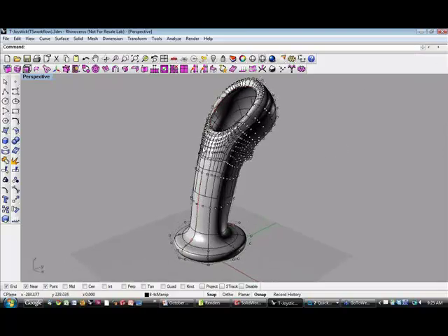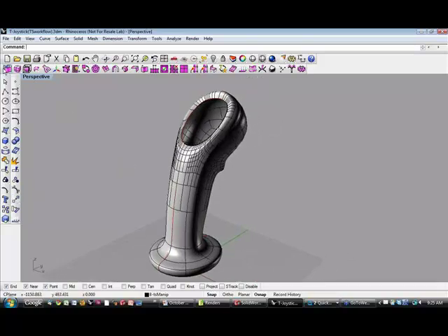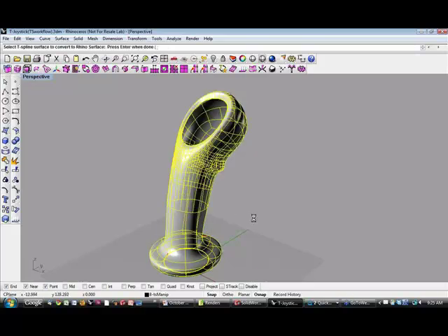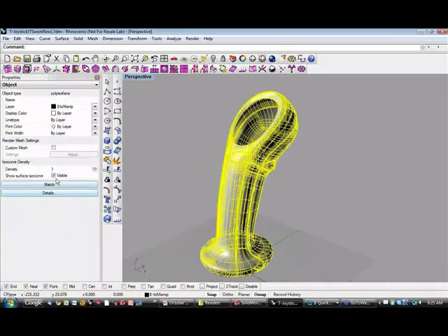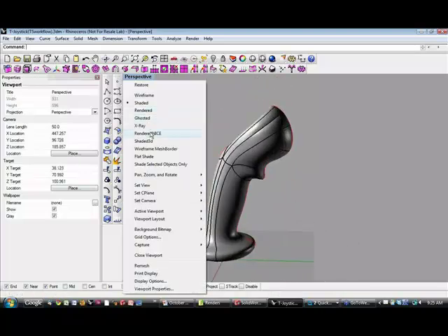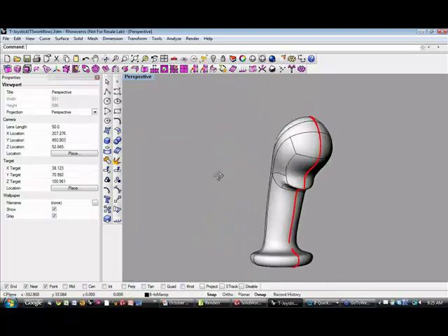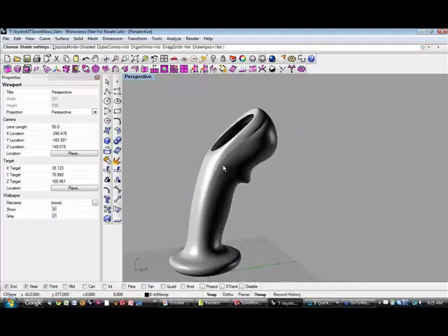Because SolidWorks does not have T-splines natively today, what I'll need to do is convert this to NURBS. But converting T-splines to NURBS is just a push-button operation. You can see here's the T-spline surface, and to convert it to NURBS, I'll just click that icon and click the T-spline. And you can see the actual shape of the surface doesn't change. What does change is that the T-spline needs to be split up into rectangular NURBS regions, because NURBS all have to be rectangular, but the actual smoothness of the shape will not change at all.